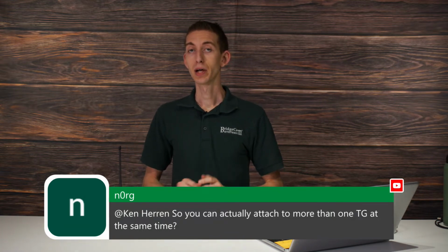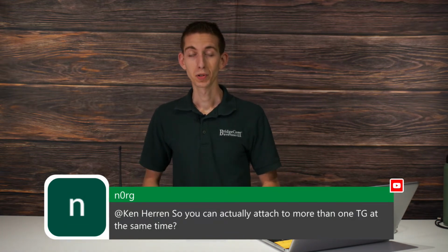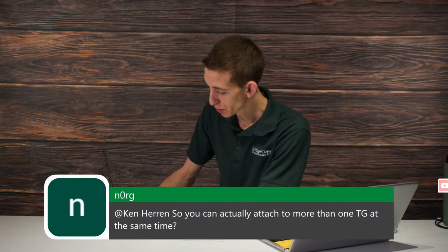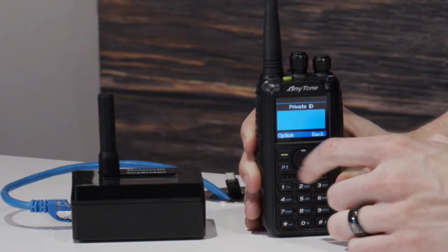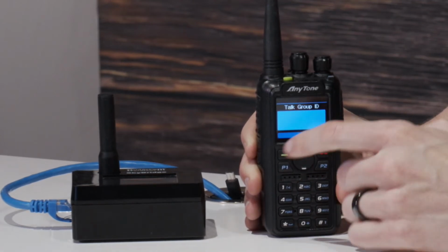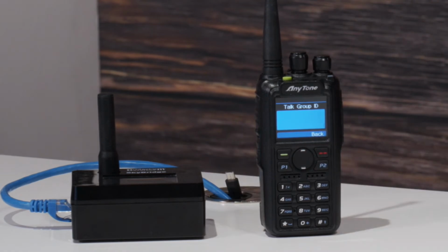So if you have a lot of repeaters in your radio, there is another way to select the talk group. You can just hold down the 0 button right here and actually punch in, you press the pound key, but you'll punch in that talk group number just like that and key it up. That's one way to select your talk group if you have a lot of repeaters. But if you mainly just work with a couple, you can actually just create those channels so you can scroll your channel knob through the talk group. So absolutely.